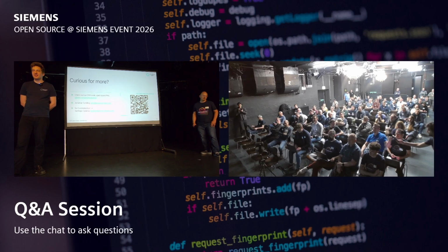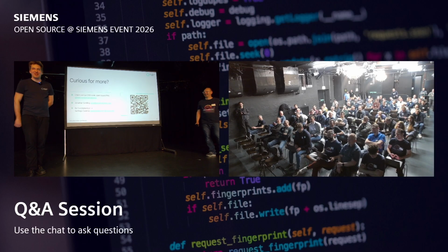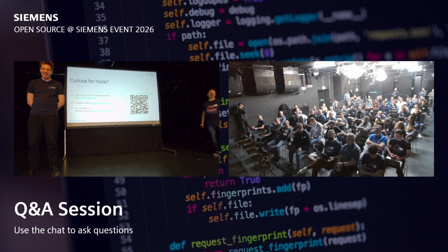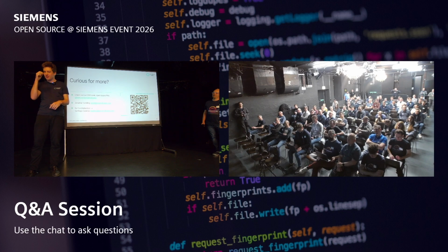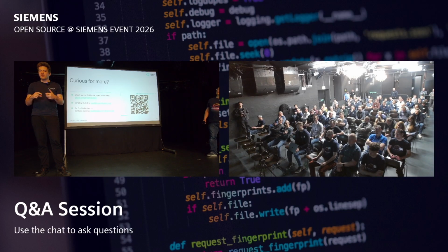The thing is, that's a little bit of an unfortunate message for you, I think. Stellarators are just so stable that you don't need so much control. But there's always a but. You do need certain control systems for a stellarator. If you look at time trace plots with multiple quantities, you always see that, for example, the plasma density has a set point and then wiggles a little bit around it. This is because the PID controller for that density feedback is not really tuned properly, as happens when you have just spent 10 years building the machine and then you want to operate it.